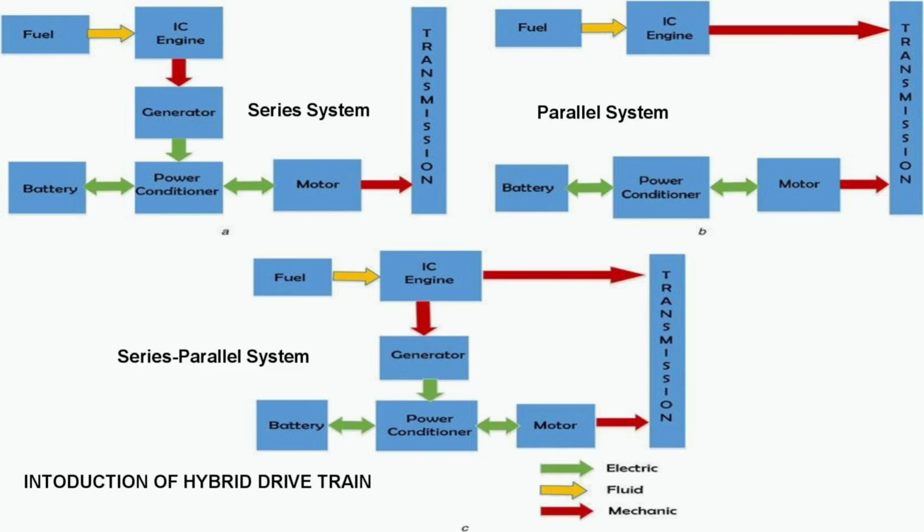The advantages of parallel hybrid drives are that both engine and electric motor directly couple torque to the driven wheels and no energy form conversion occurs, hence the energy loss is less. Next, compactness, due to no need of the generator and a smaller traction motor.